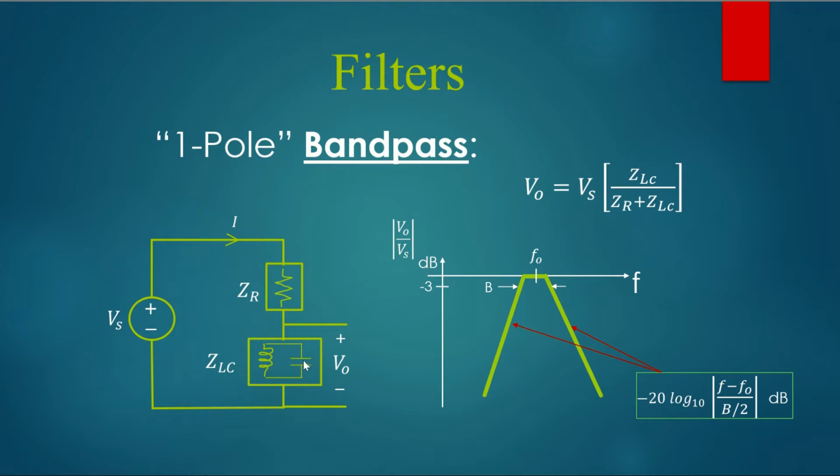It turns out, because of the mathematics that we go through in the university course, you can show very clearly that at one particular frequency, these two exactly cancel each other in the sense that the impedance from here to here becomes infinite. And so when that happens, ZLC is infinite, or a very large number.